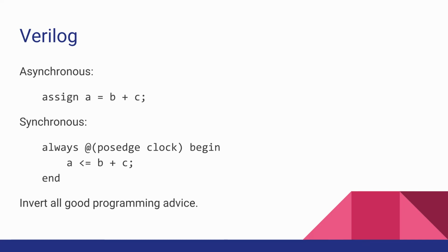And in practice, literally you could write here, if counter is odd, then do this. And then if it's odd, it'll latch the sum into A, and if it's even, it'll latch A into A. And so you're always latching, because the clock is permanently attached to A. And the question is, where is it getting it from? So if it's disabled by an if statement, it'll just feed it back into itself, and the compiler does all that for you.